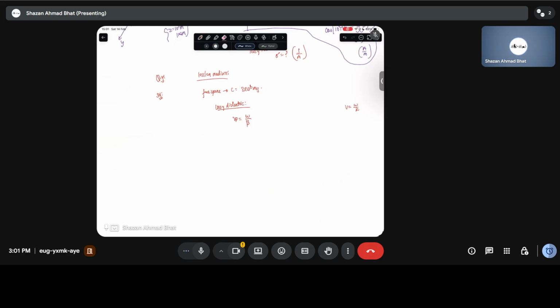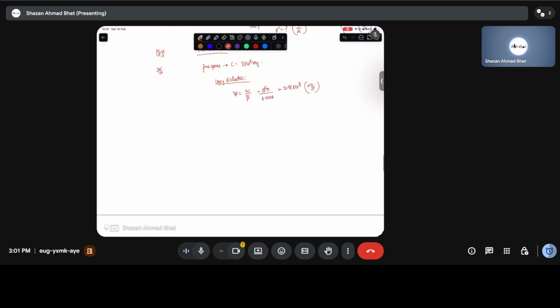It's the wave phenomena. You write the frequency as velocity into propagation constant. So this is exactly 10 to the power 6 pi divided by 0.00108. So you get 2.91 into 10 to the power 8 meter per second. So you see the velocity has reduced. So the wave propagates.